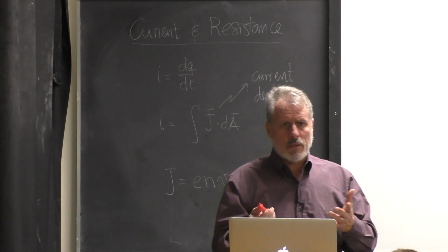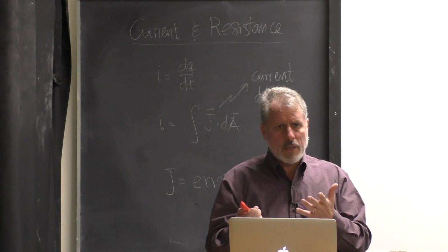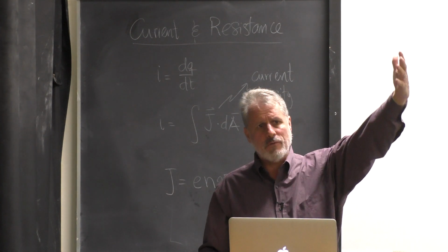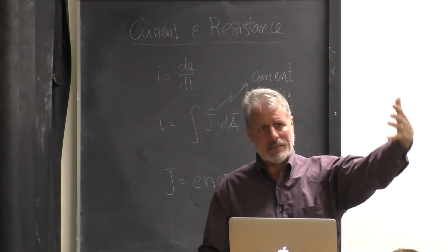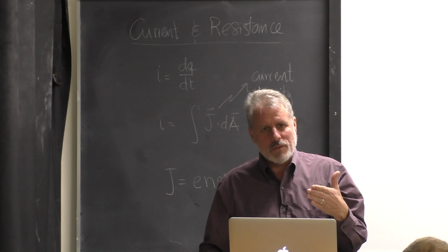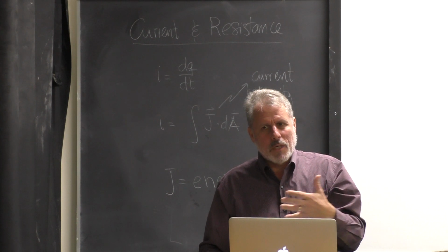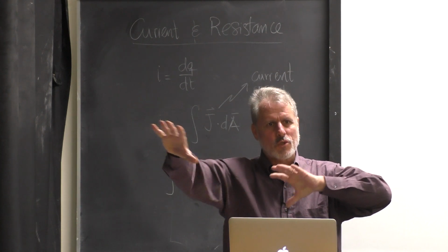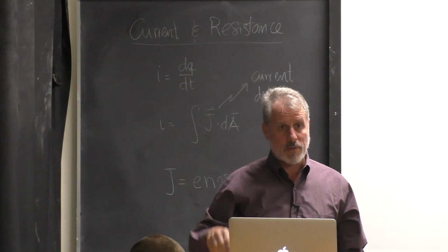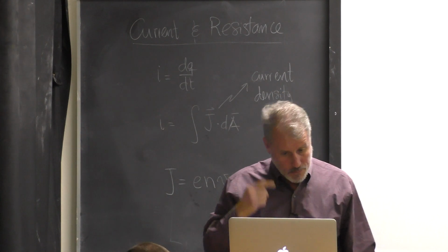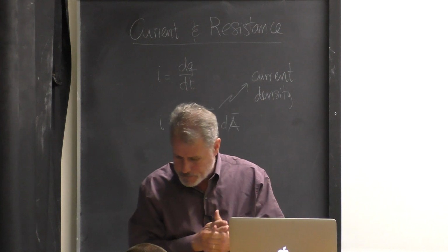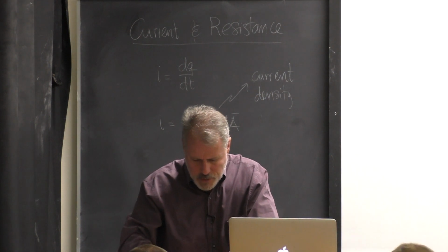We'll also see why the combination of those two is fairly effective. If we have a source far away, the best way is to have high alternating voltages, AC. If they were very close by, then distance is not an issue anymore, and you can have DC sources. But because of the separation between the source and the users, we use alternating voltages that are very large at the source. You can convince yourself by playing with the relationship between V squared, the power, and R. Okay, so let's look at some of these questions.